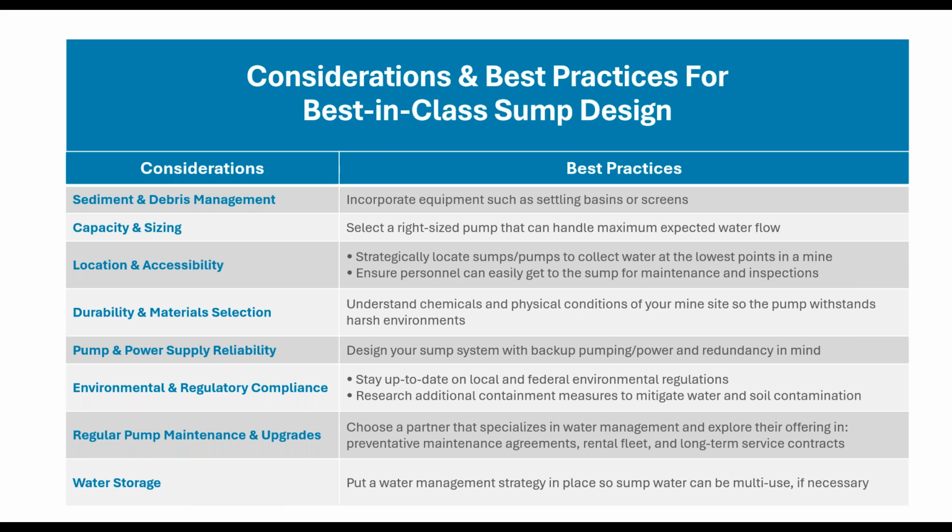Location and access. You heard me talk earlier about the water is sometimes in the wrong place. Well, I take that to mean sometimes the sump is in the wrong location. So it's really important to strategically locate sumps to collect water from the lowest points of the mine, right? Let's not try to fight gravity.